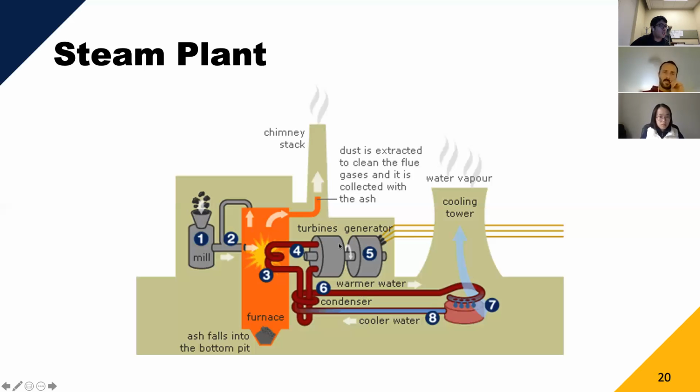But the water going through the turbine itself is in a closed loop, and that ensures that this turbine can operate at maximal efficiency, because the water here is really purified. It doesn't have impurities that will damage the turbine or make it operate less efficiently. And the water that's cooling it is actually the stuff that you see evaporating out of the cooling tower.